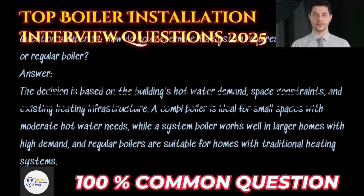Question number 14. How do you determine if a system requires a combi system or regular boiler? Answer. The decision is based on the building's hot water demand, space constraints, and existing heating infrastructure. A combi boiler is ideal for small spaces with moderate hot water needs, while a system boiler works well in larger homes with high demand, and regular boilers are suitable for homes with traditional heating systems.